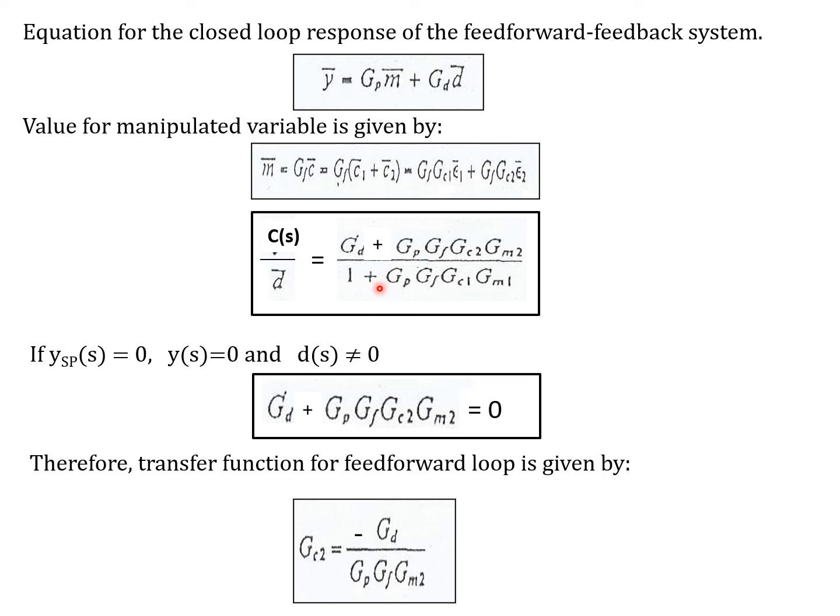This is still the normal characteristic equation, and once you have a characteristic equation, you still have to be careful because you can have an instability problem. Once we introduce feedback, you get the instability problem, and that can be checked through this characteristic equation. But with just feedforward, you don't have the feedback, so you don't have the characteristic equation issue or a stability issue. That's another advantage of using just feedforward. But the minute you combine it with feedback, stability issues come into the design, and you also have to look into that.